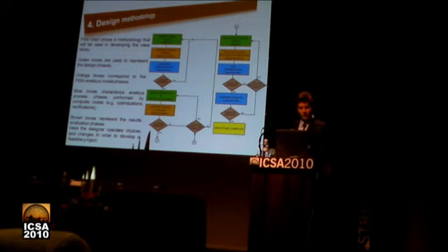In the orange boxes there is the analysis model. So you have to put your model in some software and some tools to help you to create the analysis model. And then you launch the topology optimization or another kind of optimization. And if the result is satisfactory, you can continue with a refinement of the shapes, the choosing of the material, and create other analyses. The last analysis in this case is a size optimization. Then you can run further verifications, and if the result is really satisfactory, your structure is complete.